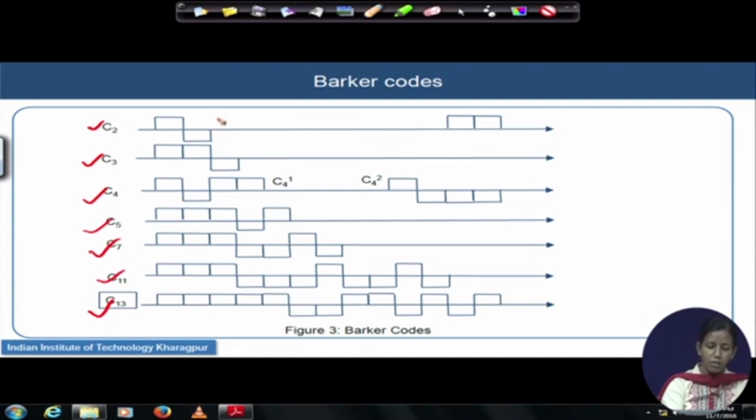Remember the Barker codes of very short length, C2 and C3, and even C4, are not of much use in practice, because even for synchronization at least a certain length of the codes is required to estimate the parameter of our interest. And mostly for the timing information extraction, we try to utilize these Barker codes.